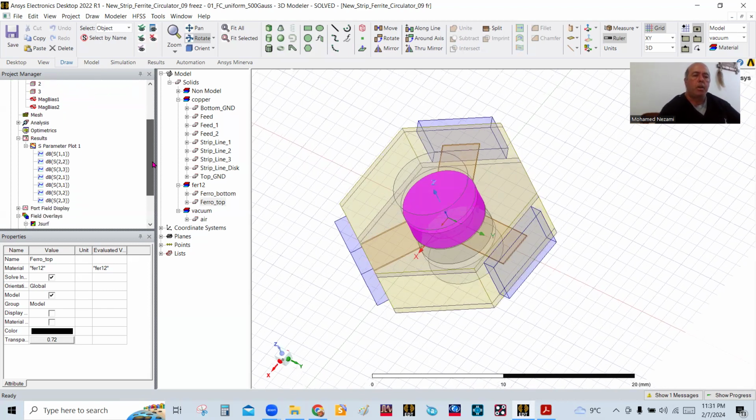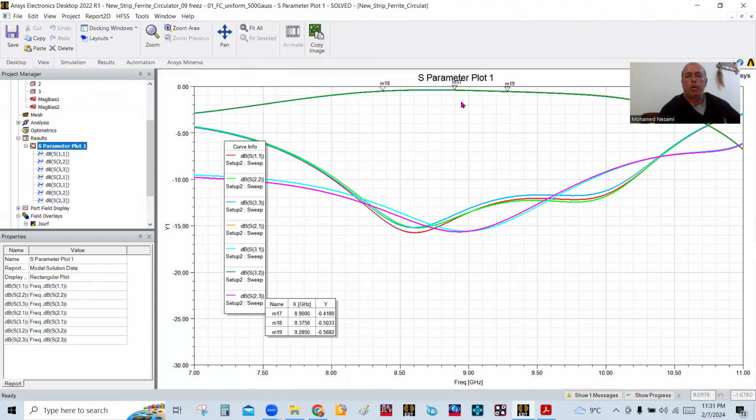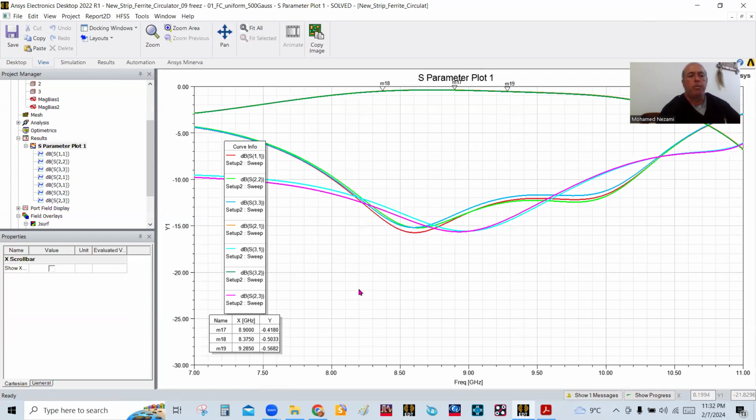This design here was basically done for the like the microstrip that I did. This was done for 8.5 gigahertz as well, similar to the microstrip case that I covered in the second video of this series. So you can see the return loss, the isolation, and the passband in here with the loss about a gigahertz within 0.5 dB of loss.